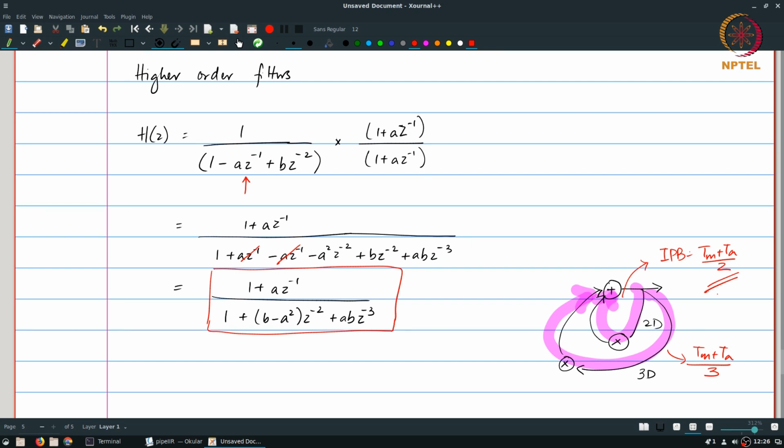This is not restricted only to IIR filters. One of the places where it has found significant use is the Viterbi algorithm, where it turns out that there is a similar kind of loop. There is a loop in the structure where you need to add a certain metric value, compare it against the previous metric, and then decide which one is the survivor. Once again, it looks very similar to an IIR type of filter. The operations are not directly multiplication and addition; in this case, they are addition and comparison. But because addition and comparison follow the same kind of mathematical properties, we are still able to do a lookahead, and a similar kind of reduction in the critical path or the iteration sample period can be obtained.